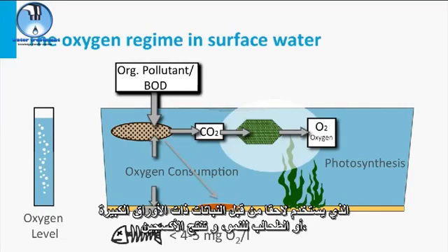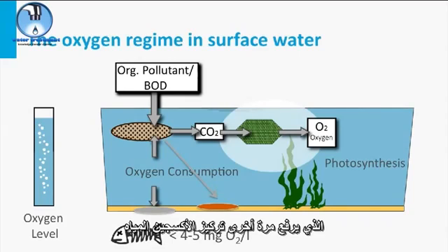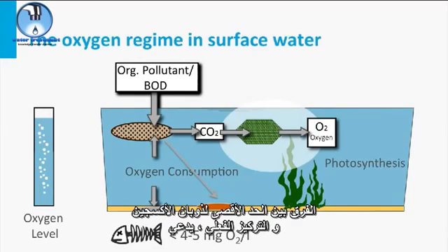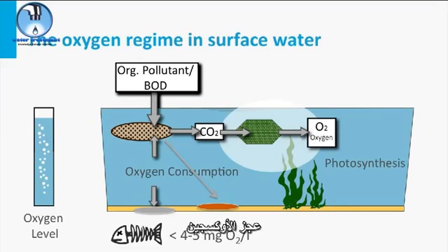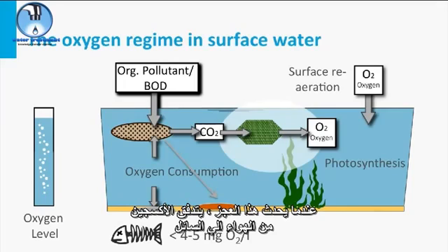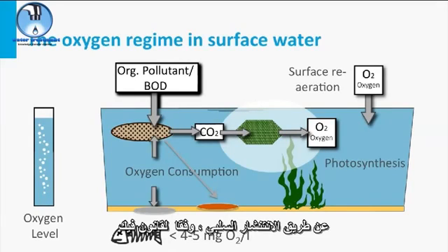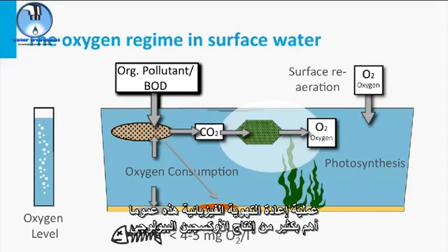This CO2 is subsequently used by macrophytes or algae for growth, while producing oxygen, which again raises the water oxygen concentration. The difference between the maximum oxygen solubility and the actual concentration is called the oxygen deficit. When such a deficit occurs, also a net flux of oxygen from the air to the liquid will start via passive diffusion following Fick's law. This physical reaeration process is generally much more important than biological oxygen production.